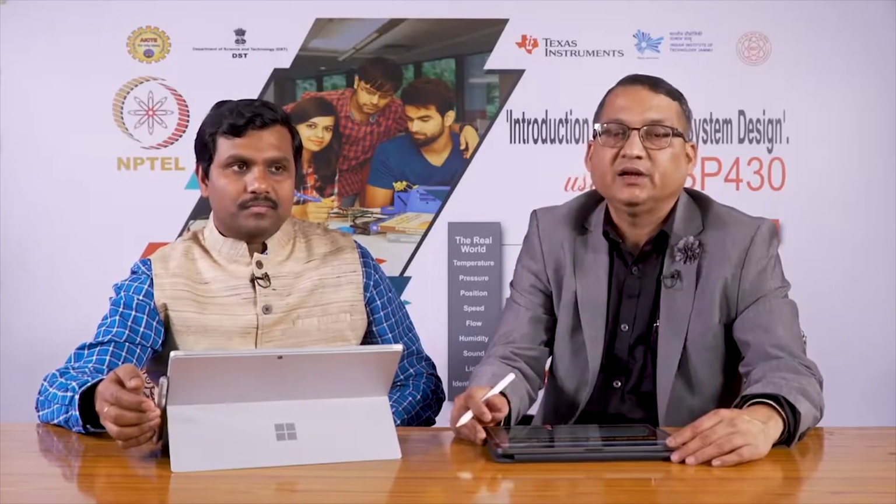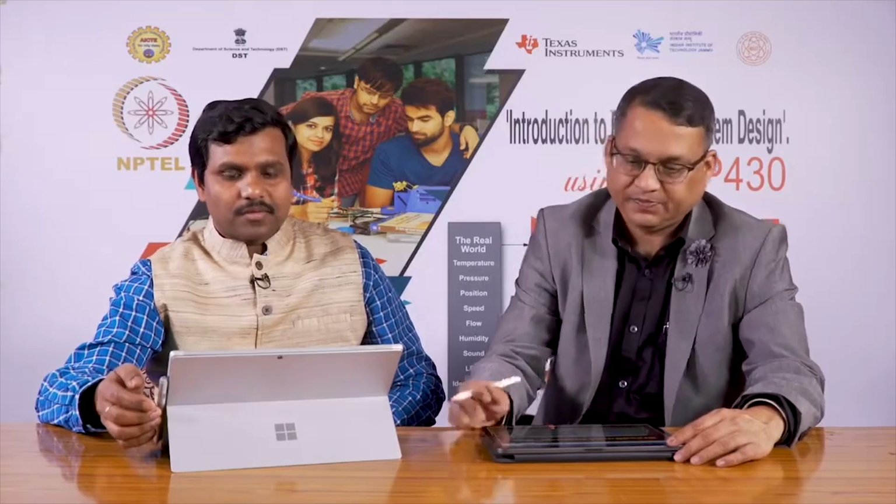So, this is the structure of a breadboard, and this makes it very convenient to quickly prototype a circuit. You do not need to wait for any PCB. Inserting a component and making a connection does not take much time compared to soldering, and therefore, this is a much preferred approach of prototyping circuits. But because of the nature of these wires, there is a lot of mutual inductance and it is not very suitable for high frequency circuits.